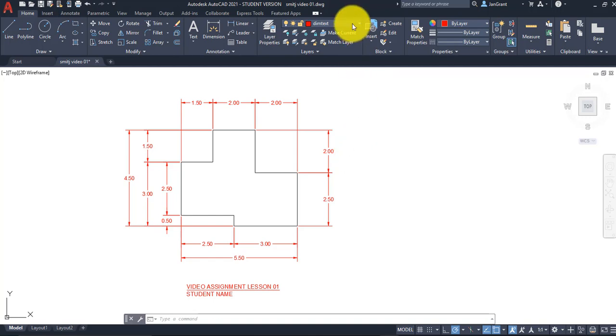We'll just leave it at that, understanding that it's a layer that is created by AutoCAD. Also, layer 0 is something that we'll come back to in describing how to use it with blocks, and we'll stay away from putting objects on that layer for now.